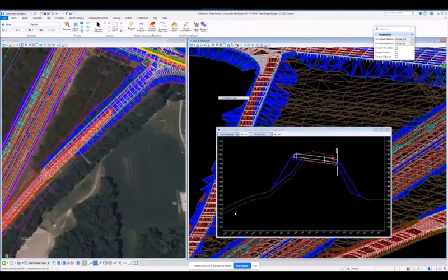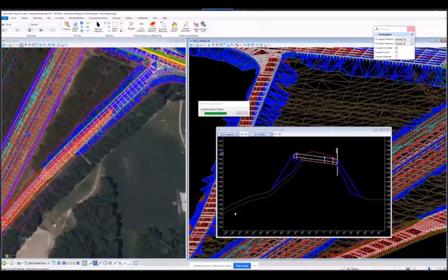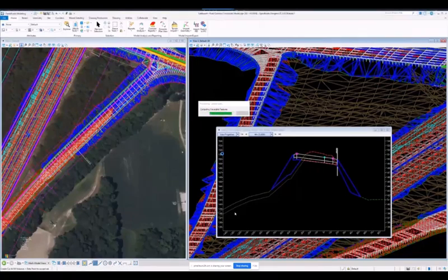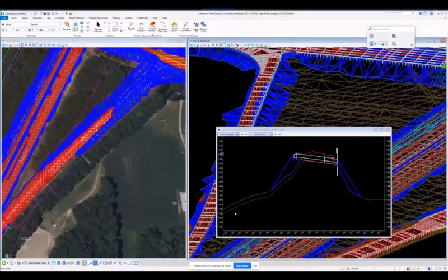And now instead of my fill running to existing ground, I'm taking my existing ground and digging out a foot. I'm augmenting my existing to be something different. So in this case, shouldn't my fill reflect that? I have to fill in the hole. I can't build a road on air.